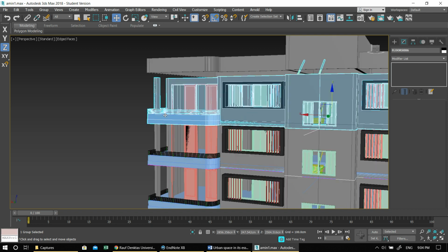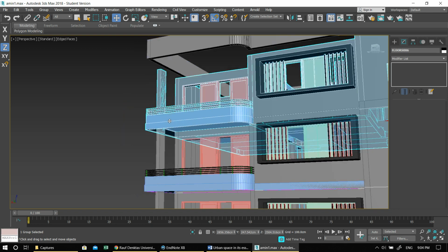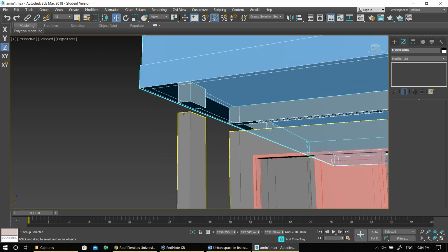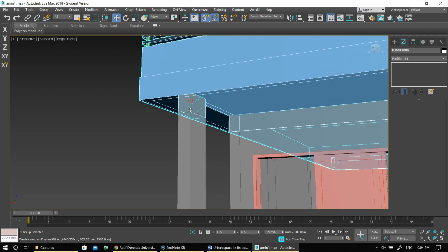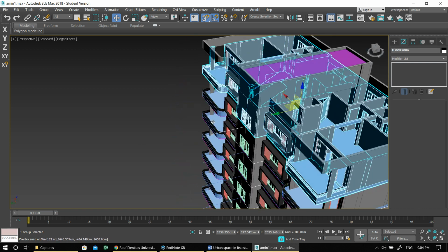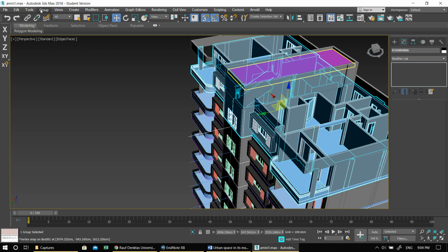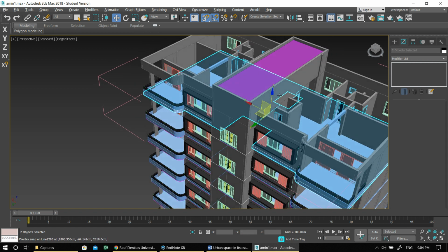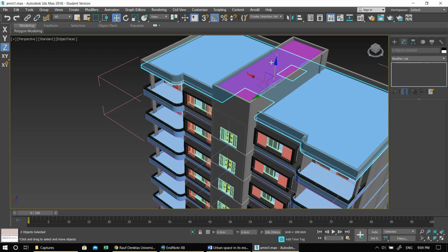Bring it up again. I mean, we have to deal with our mistakes, so this is another lesson. You have to always deal with the mistakes. Like I did something, I did not pay attention closely to that, so I have to deal with the consequences of doing a few steps again. Alright, so it looks okay, everything looks okay. Again, I go here, group. The lesson here is that you always close the group after you finished editing it. So that's the lesson. So control here, shift S, snap off, bring it up. Okay, go to group, close the group.